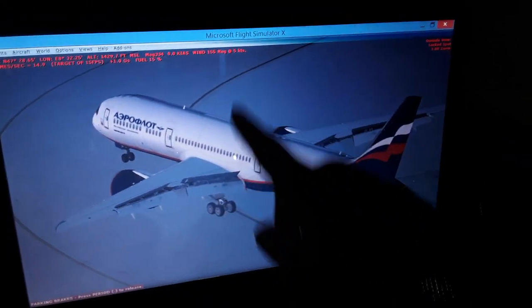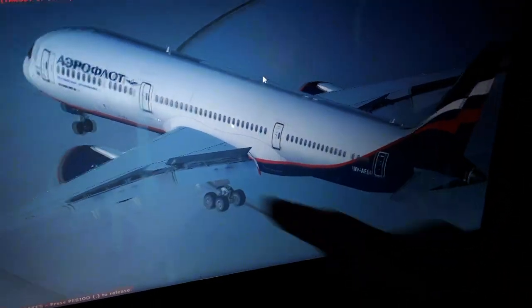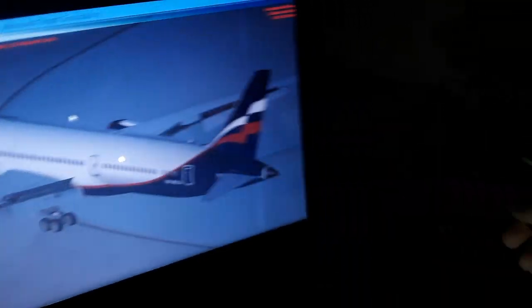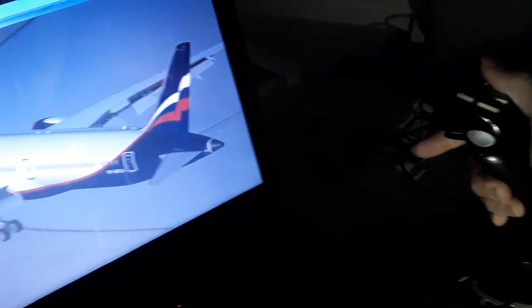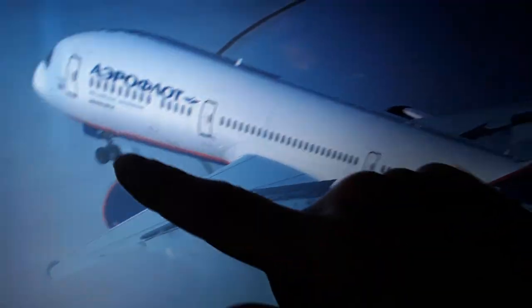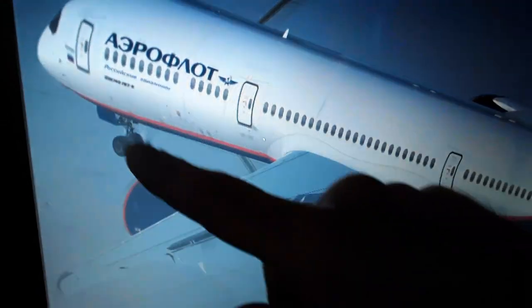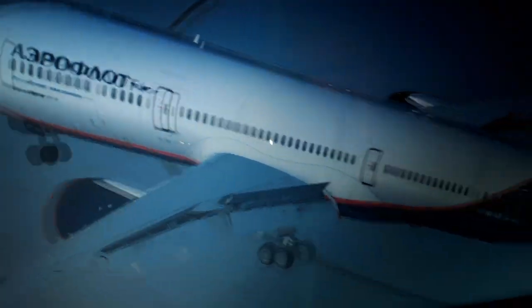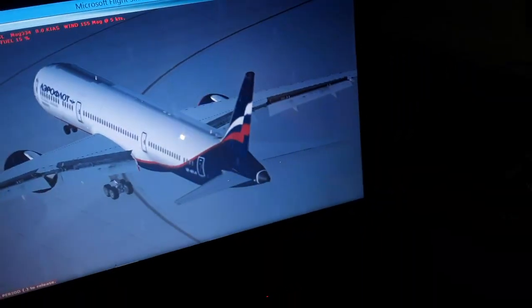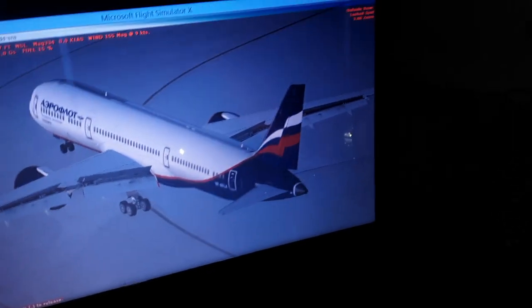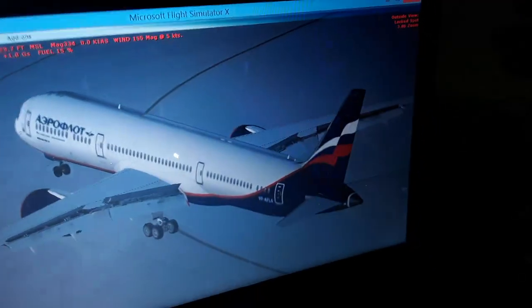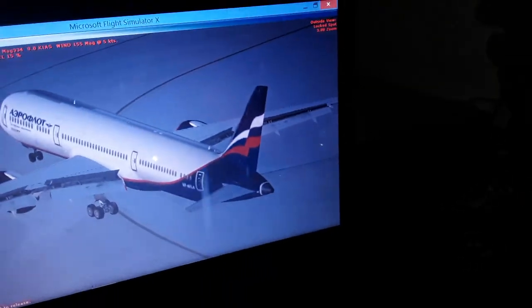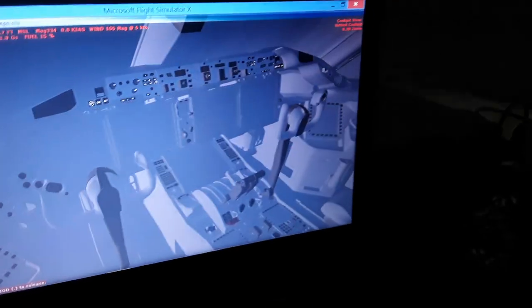When we accelerate further above 80 knots or 144 kilometers an hour, the rudder only controls the aircraft in takeoff, as you can see, left and right turns, and the forward nose wheel from the computer is locked to 0 position or half of 1 degree deflection, very small deflection. Also when we land the aircraft, first we have the rudder, and then as we slow down below 80 knots, the nose wheel becomes activated from the computer. So this is how we control the yawing of the aircraft.